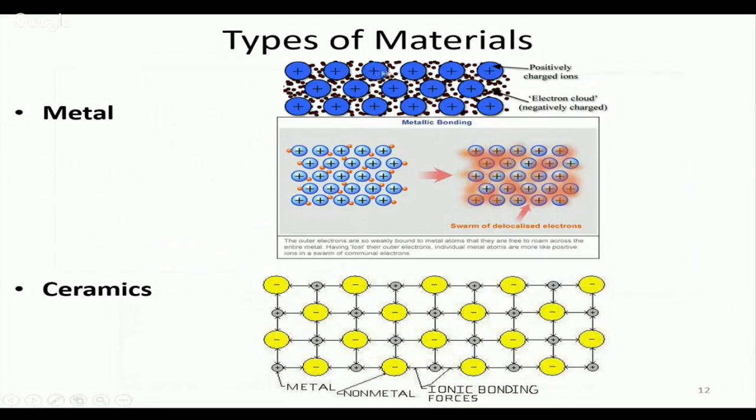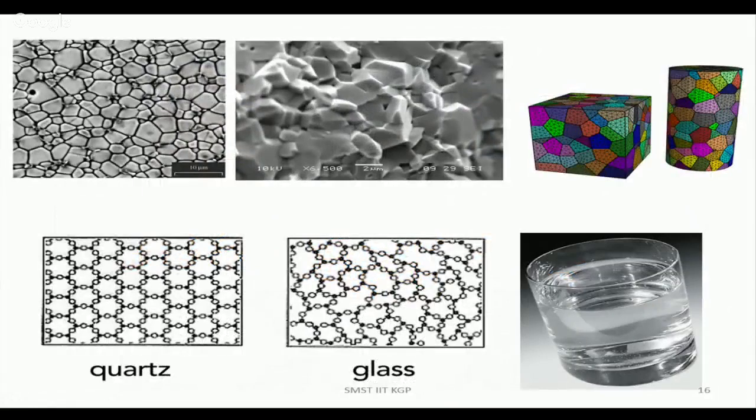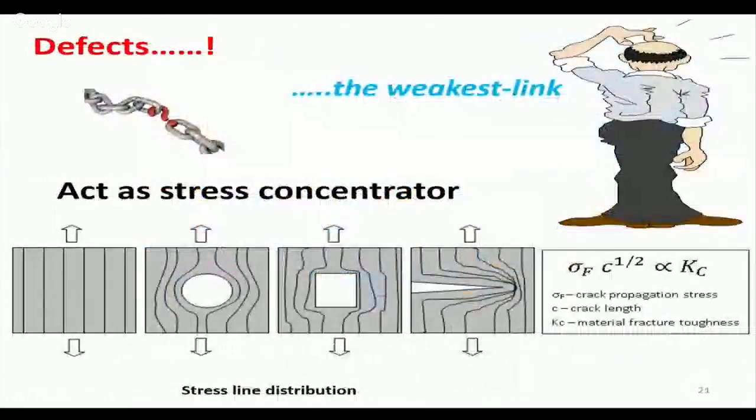One plane can slip from another plane, like in graphite, right? So this notch, which acts like a stress concentrator, will actually be rounded. Then as it is rounded, the stress which was acting on a very small area will be divided over a larger area, and eventually the stress will be distributed.